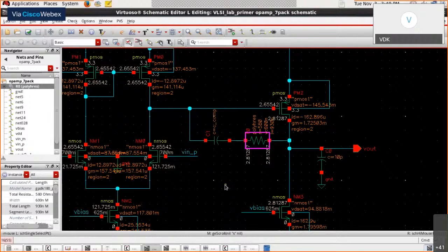So while in the magnitude plot it does produce the desirable effect, in the phase plot the phase generated by this zero, the RHP zero, will be negative, and hence it degrades the phase margin drastically.